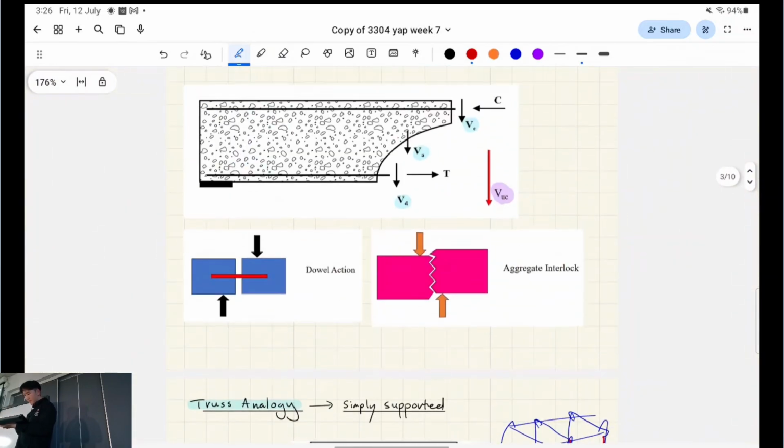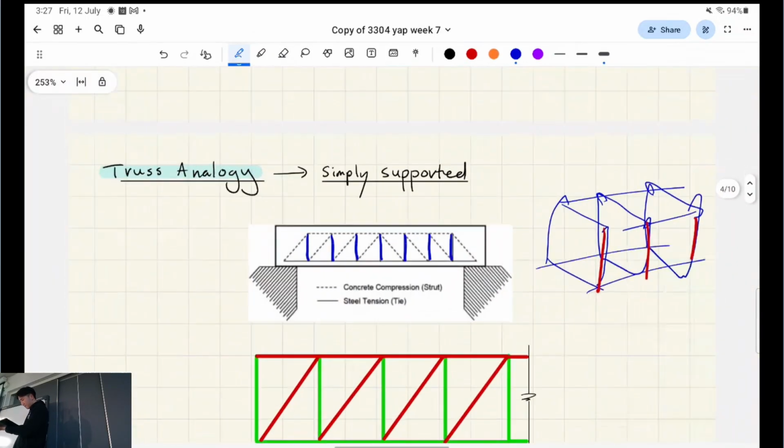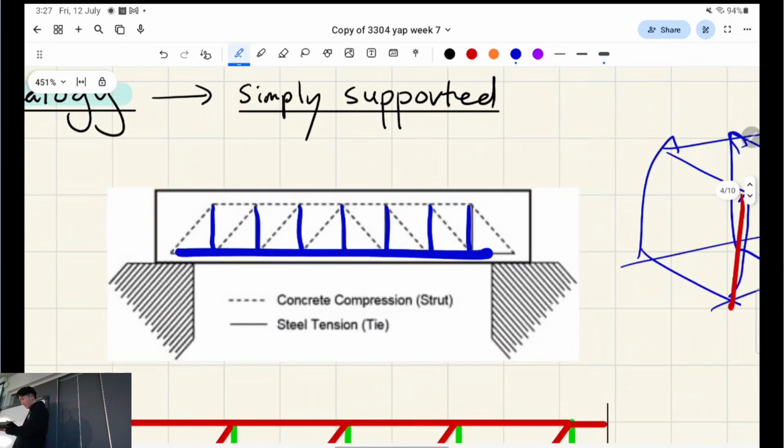So just have a look at this beam, right? Do you remember how we've talked about that top axial layer being in compression for a simply supported beam. And we've talked about this bottom layer being in tension, right? So in our truss analogy, these axial bars still, it's still consistent with these roles, you know what I mean? So like at the bottom, this steel is taking on tension, right? The bottom layer is in tension. And in a simply supported truss, you're going to find that the bottom layer is also going to be in tension when the truss is bending like a simply supported element, right?